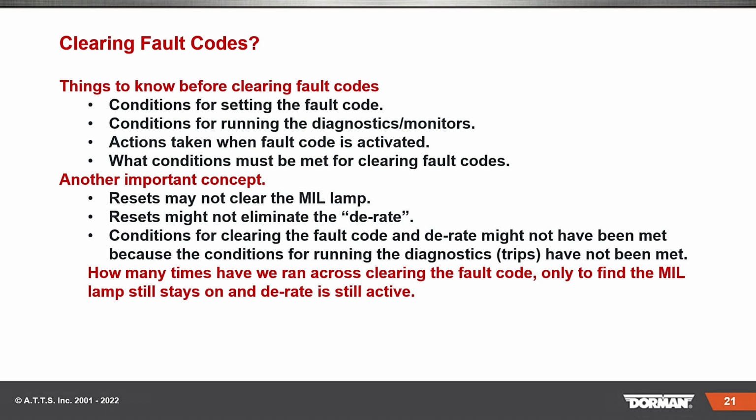What conditions must be met for clearing fault codes? Another important concept: resets may not clear the MIL lamp. And I know you guys have run into that. Resets might not eliminate the derate. Conditions for clearing the fault code and derate might not have been met because the conditions for running the diagnostics trips have not been met.